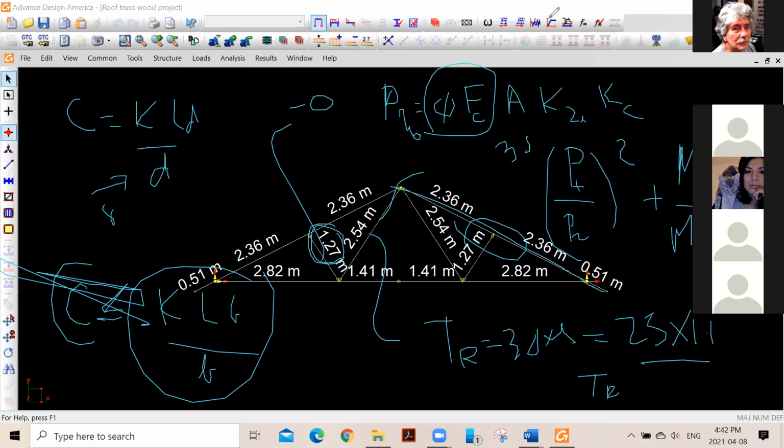See, what happens in the top chord is that you have an axial force in the top chord, which is in compression. And on top of that, you have these bending moments. So therefore, you've got to take the bending moment here and the axial force there. So this becomes your MF value, and this becomes your PF value. Now, the PR is very simple. You have sheeting laterally supported, so it's as if you're designing a stud wall. You go get the value in the stud wall, okay? And the MR is very easy. You simply go to the joist selection table and find out what the MR is for case 2, and that's where you get your PR and MR values.